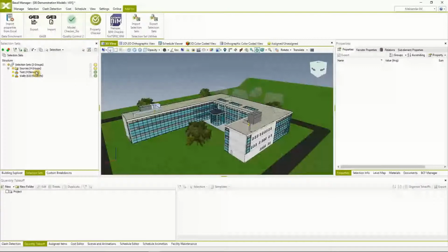There are also some additional simple examples like this one, which actually organizes the walls into bearing and non-load bearing walls. So you can separate the walls category elements by this specific property, and you can easily select them and distinguish them in the model.